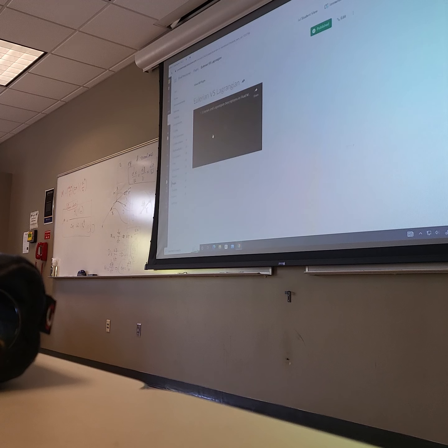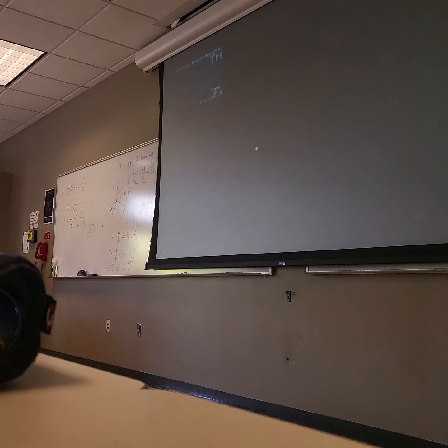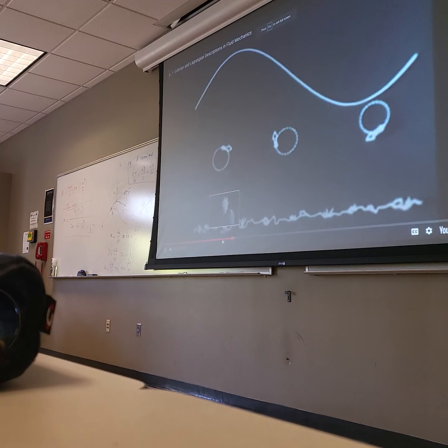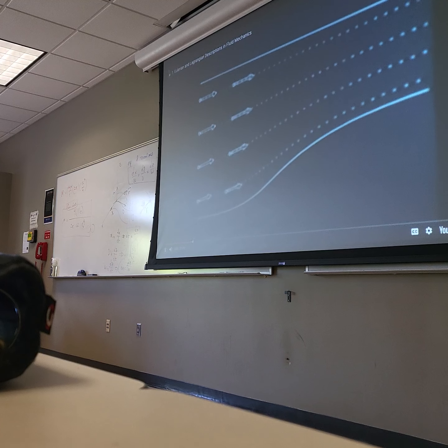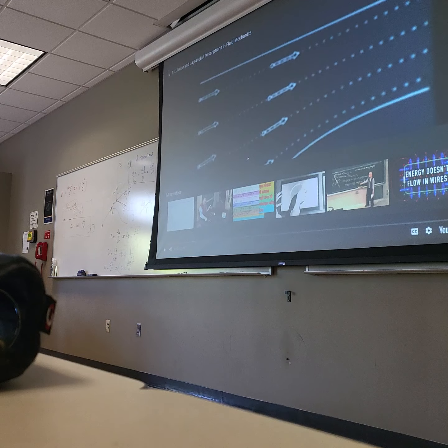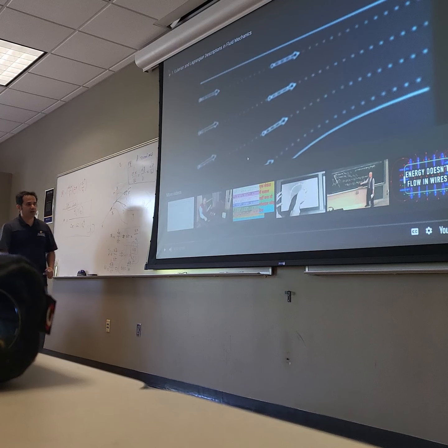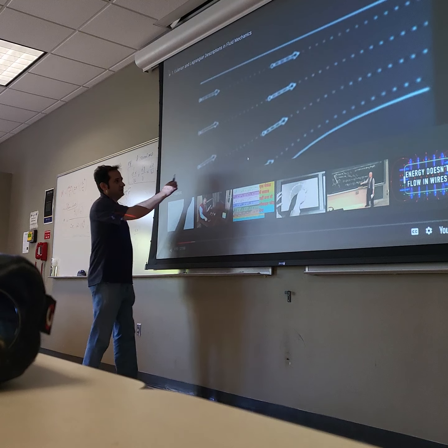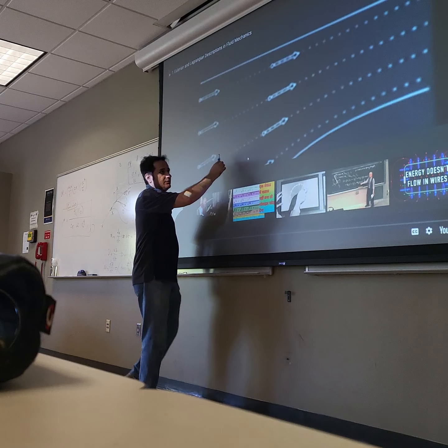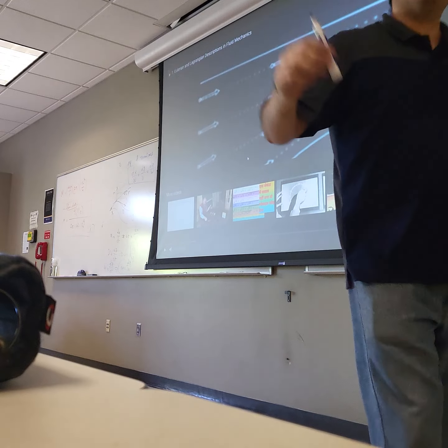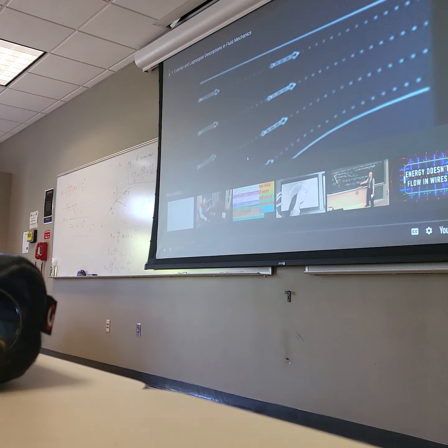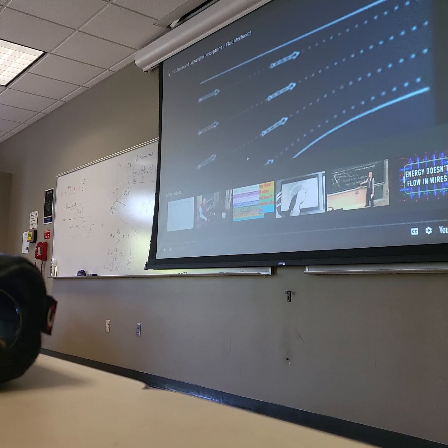Eulerian versus Lagrangian. So let me make this short. If you follow a particle in the field, so let's say there is a particle here, and I follow it, just like a person, I follow the entire history of what it's doing in the field. That's called the Lagrangian approach. As you saw in dynamics and vector statics, all we did was the Lagrangian approach.